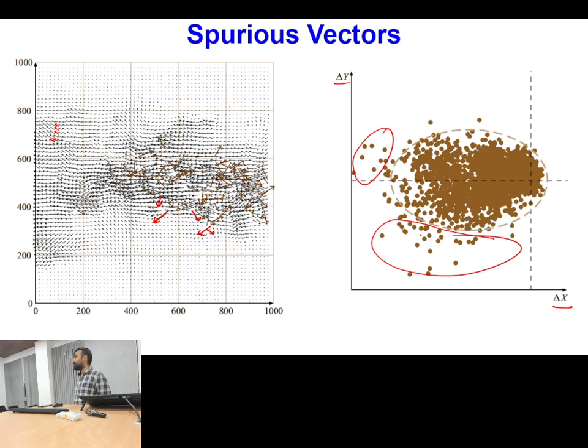Whenever you are doing PIV measurement, once you have done the analysis, your task is not over just by plotting the velocity vectors. You also have to find the spurious vectors or outliers. Typically, in multi-phase flow measurements, these spurious vectors are more prone to appear near the interfaces, because near the interfaces you may have virtual particles because of reflections and refractions.